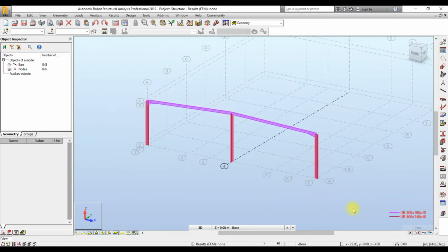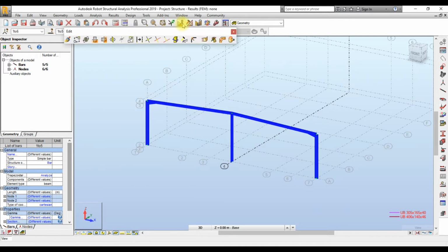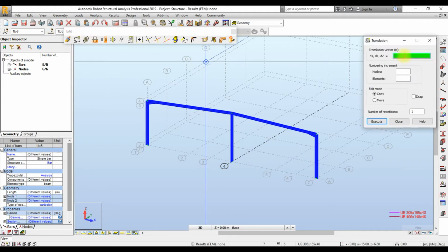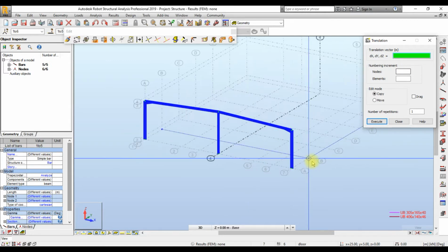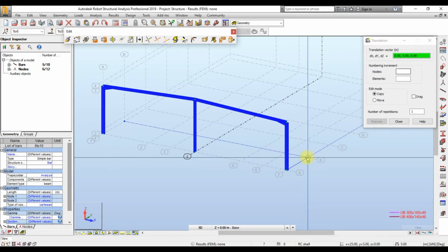Then you can highlight this guy here. After highlight, you come down here. Look at this arrow here. It is the edit button. Look at this. Is move copy. We have the rotation, horizontal mirror, vertical mirror, planar symmetry, and now I'll come back to your move or copy command. So now I want to move this on each of these nodes. You can try this like this by hitting on this base point here and putting it downwards here.